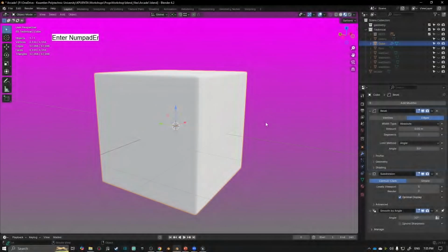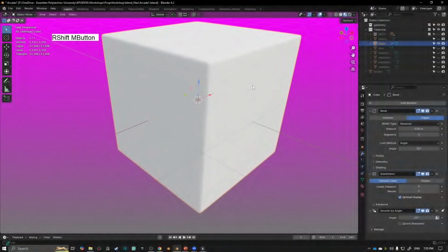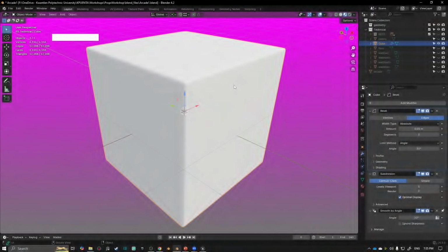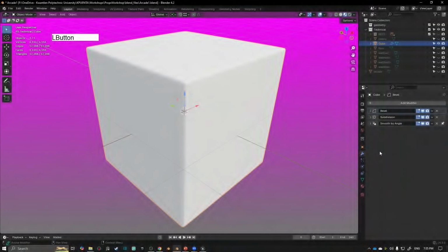If you manually insert edge loops, you're doing more what I would call destructive editing or modeling. You're doing stuff by hand. Whereas if you're using modifiers, if at any point you don't like the modifier, you can literally just turn it off and on. You can say, okay, well, what happens if I move it later in the stack?